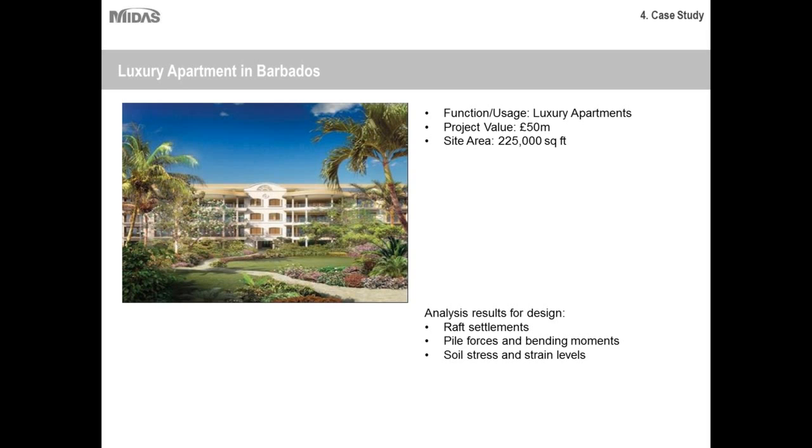And the location of this site is very close to the beach. Therefore, the soil strata is not very stable, and there they had to go for a pile raft foundation because of its soil strata conditions.